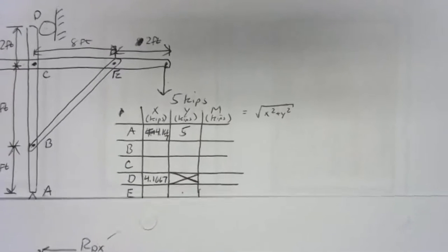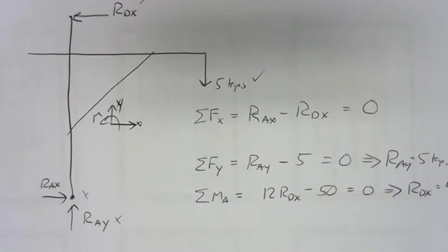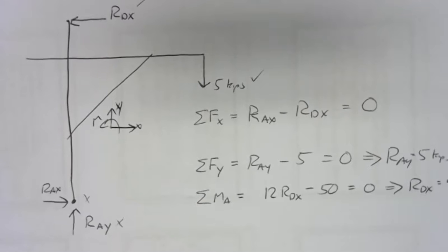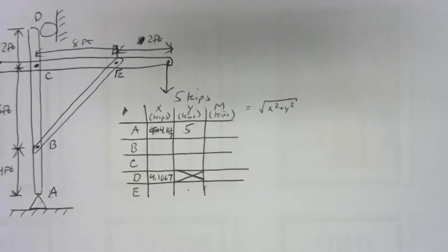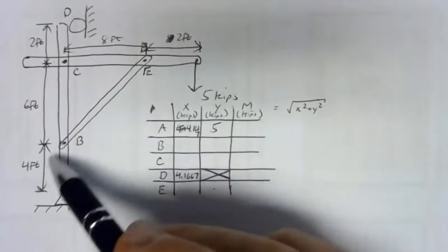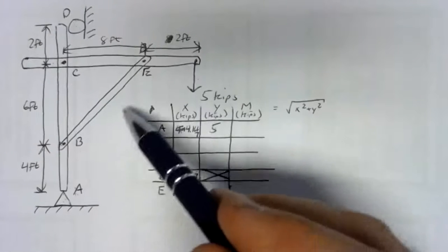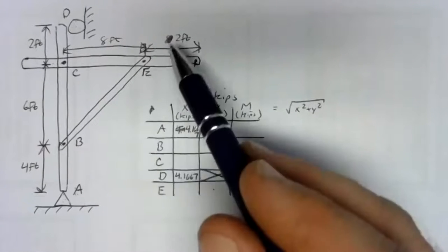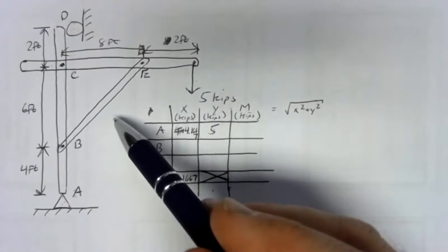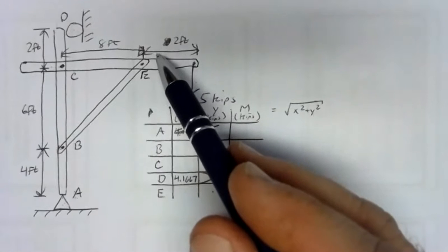So now we've got 3 numbers, and that's all we can get out of the external problem. So best case scenario, 3 equations, 3 numbers. So we've got 3 out of 9 of our unknowns. We're a third of the way done. We need another setup. So last time I gave the advice to avoid working with slanted members. Slanted members usually give you more equations than unknowns because of the way that the moments work. You end up getting more equations than unknowns.